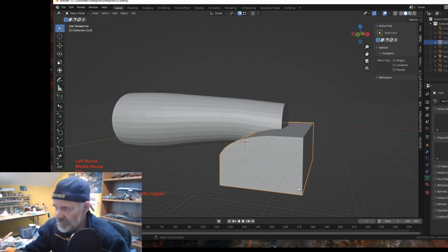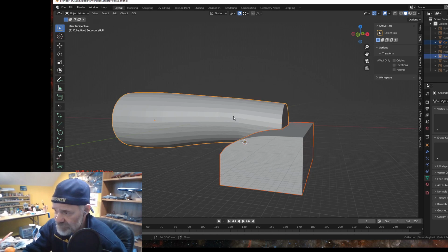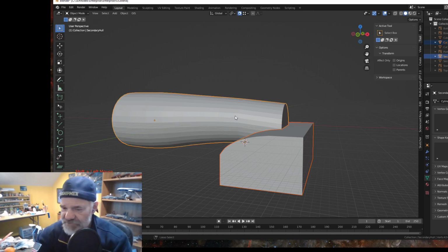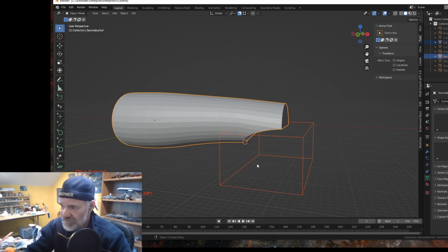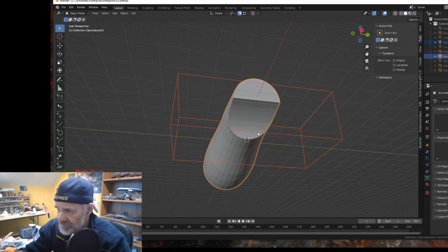Alright, then I'm going to tab out, and I don't need to make a copy because I can recreate that part that I just did pretty easily. So with cut 1 selected, hold shift, select your hull, right side control key and the minus at the same time, and we cut our ship just like that. See how that works?